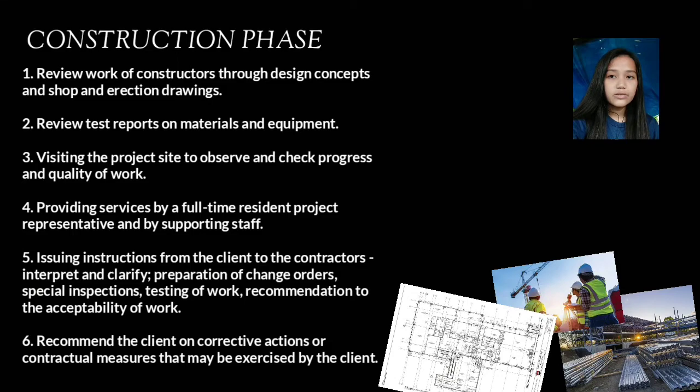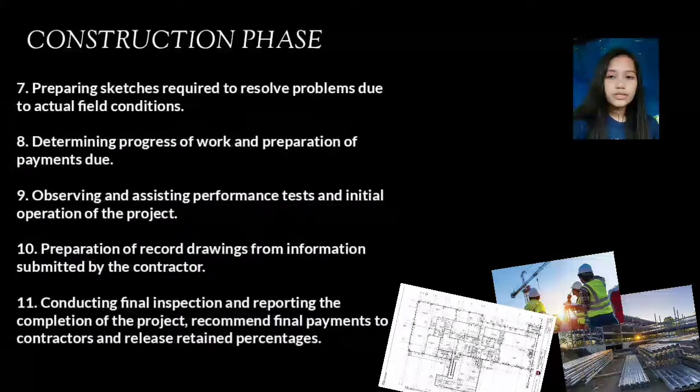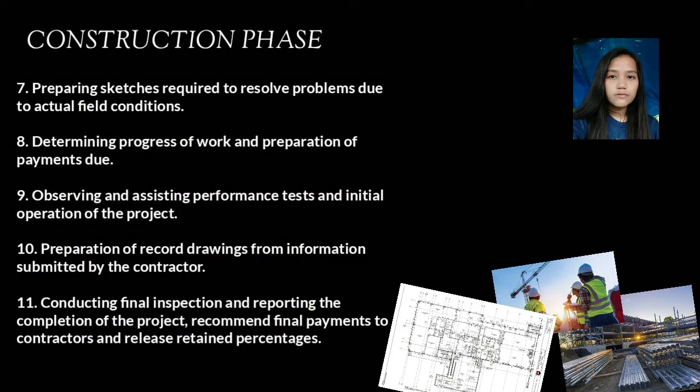Then we have recommend the client on corrective actions or contractual measures that may be exercised by the client, preparing sketches required to solve problems due to actual field conditions, determining progress of work and preparations of payments due, observing and assisting performance tests and the initial operation of the project, preparation of record drawings from information submitted by the contractor, then finally conducting final inspection and reporting the completion of the project, recommend final payments to contractors and release retained percentage. The focus of construction phase is to develop the system to the point where it is ready for